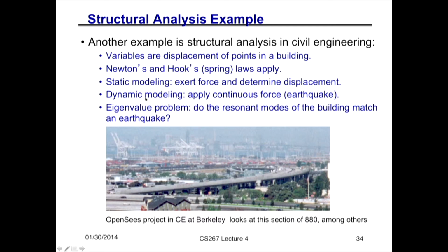You could also ask, more interestingly, the ground is moving, it's shaking, so you apply a continuous force and you ask what happens to the building. So there's your ordinary differential equation. And finally, you have an eigenvalue problem, a different linear algebra problem. So when you build a building, how are you going to be sure that no matter how the earth is shaking, because it can move in different ways, that it won't fall down? Well, what you do is you ask, what frequencies does the building like to shake at? What are its resonant frequencies?